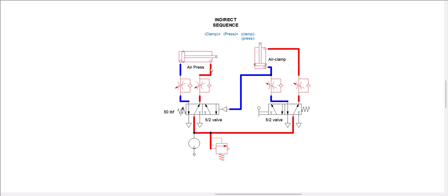We're not using any sequence valve in the circuit to create that sequence. We're just using the spring pressure to have a kind of delay to build up that pressure using a pneumatic pilot. One of the 5x2 valves is feeding the other 5x2 in here, and that's how we are getting the sequence done. Thank you very much.